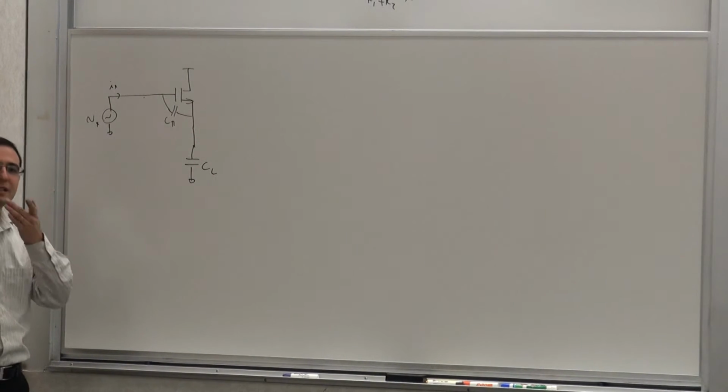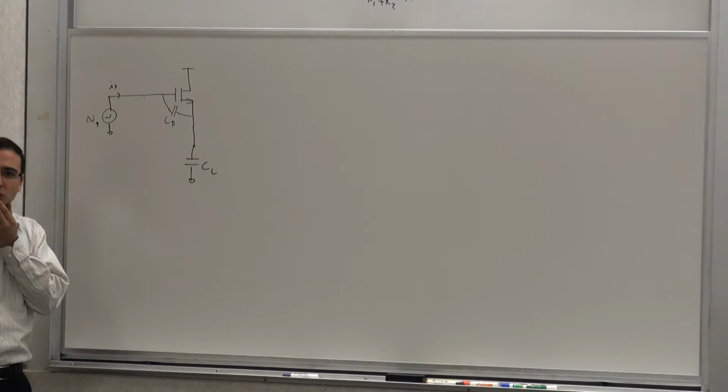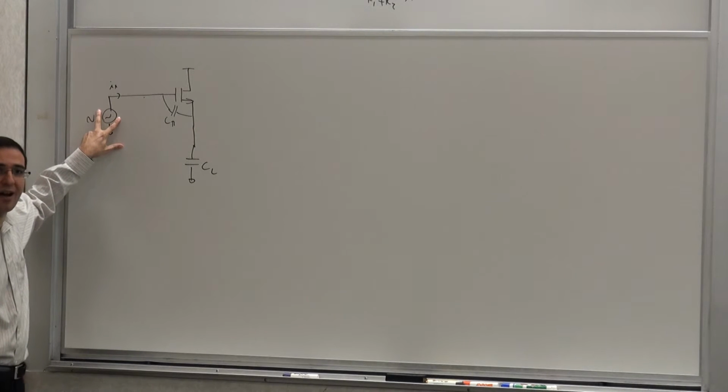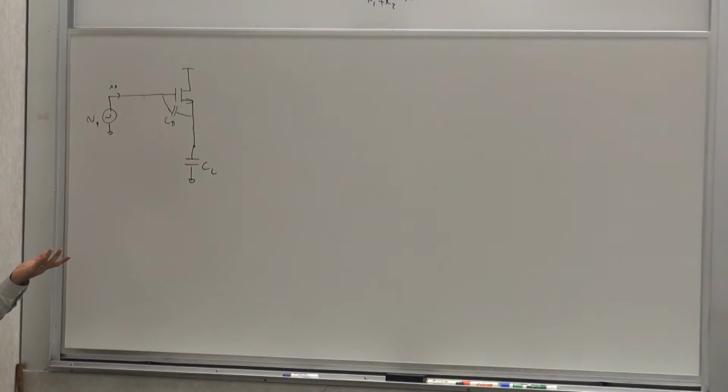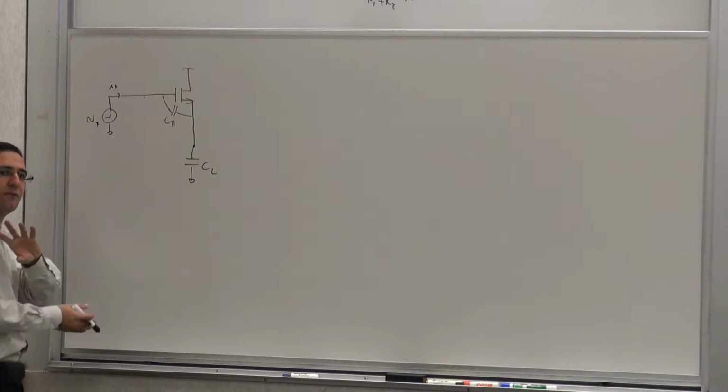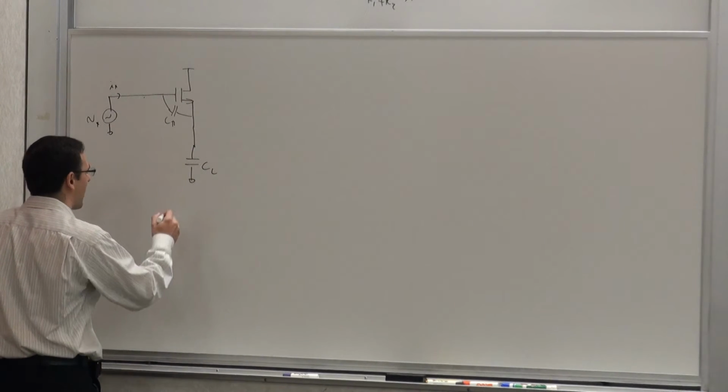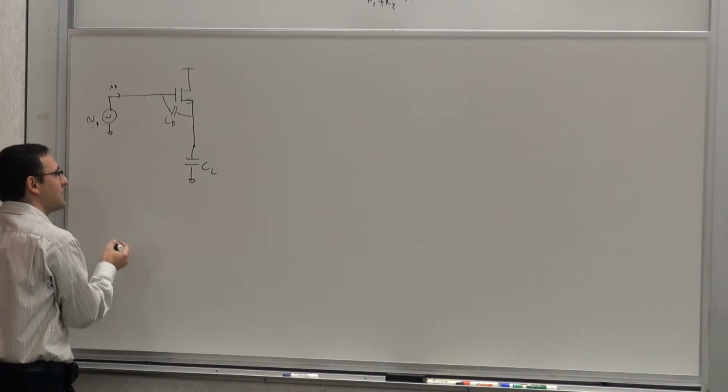Or am I calculating the input impedance now? What is my independent source? The voltage source. What is my dependent variable? Current. So I'm actually calculating the ratio of the current to a voltage. So when I apply a test voltage, I'm automatically calculating the input admittance, not the impedance. And as long as I keep it consistent, everything is fine, as we talked about before. But if you mix them up, then everything goes haywire. So I'm calculating the input admittance, fine.